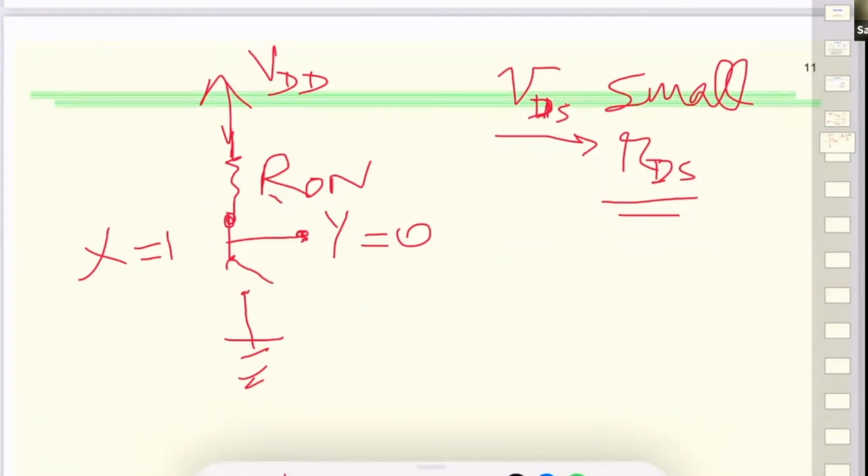So which means then we are getting signal here, and that's the case for an inverter. So that's a simplified implementation of an inverter with two MOSFETs, an N MOSFET and a P MOSFET. There can be other ways, but this is the simplest way we can implement that. Now, if you think about it, in one case,